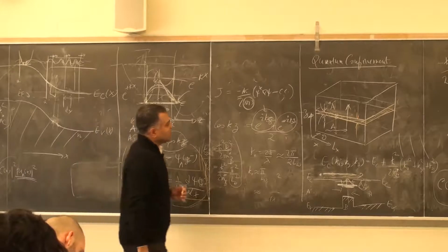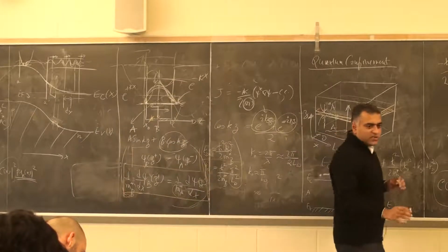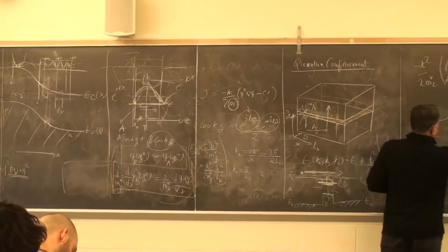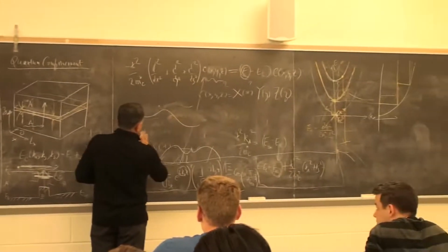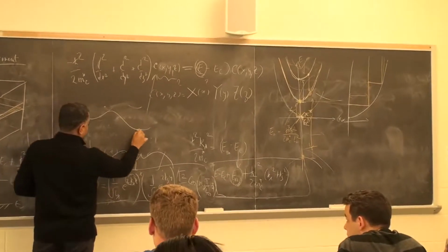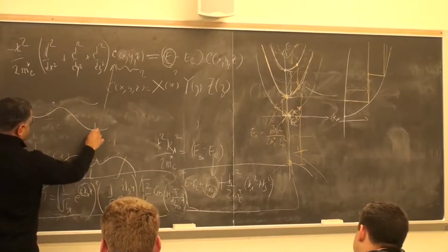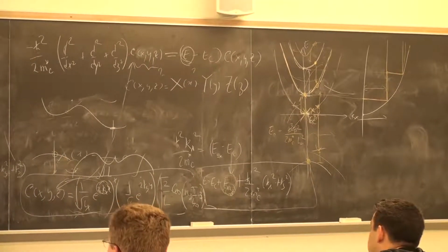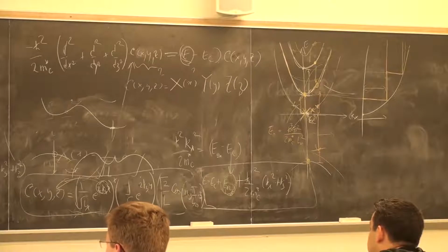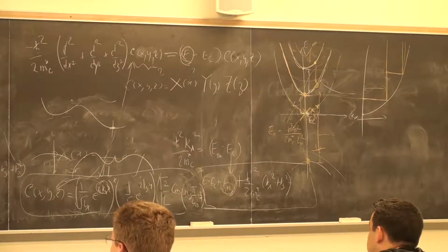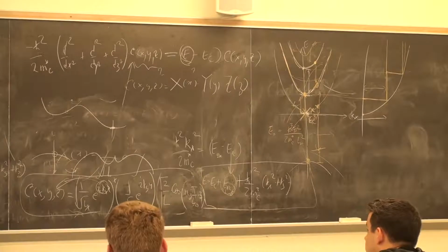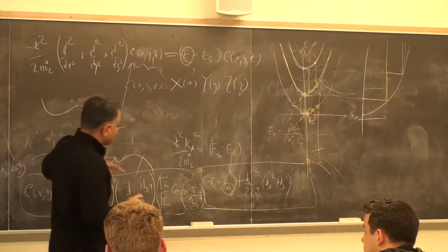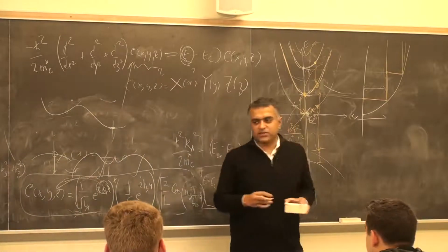Yeah, so the indirect, we'll come to this when we talk about light-matter interaction in more detail. But in the indirect band gap semiconductor, the K state of the electron in the conduction band is here, the valence band would be here, and the photon has very little momentum compared to the crystal momentum, so it is very difficult for it to match. So people have thought about very clever ideas to break this problem by quantum confinement and all, but it has never really succeeded.